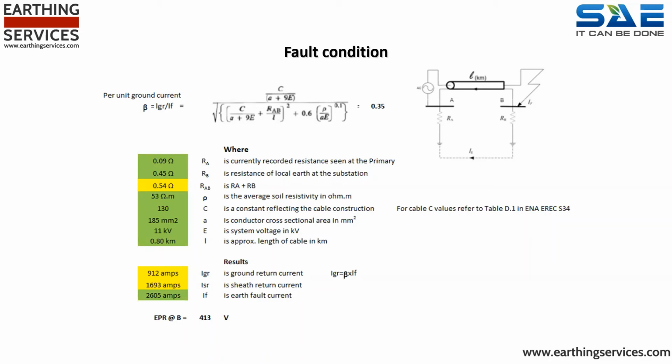However, the fault profile must consider the whole circuit. As such, it was verified that the site was connected to an 11 kV primary substation via 2 circuits from feeder 1 and feeder 2. Both circuits were 300mm triplex cable, 0.8 of a kilometre in length. These inputs fed into our calculations to determine the fault that the site would feasibly carry. The output of the calculation suggested 912 amps would be the appropriate level to carry out all touch, step and transferred voltage assessments.